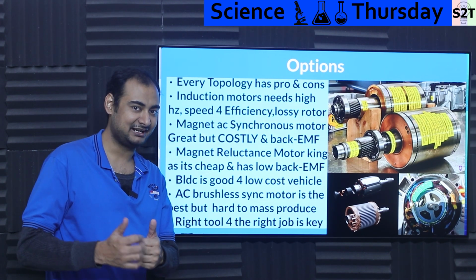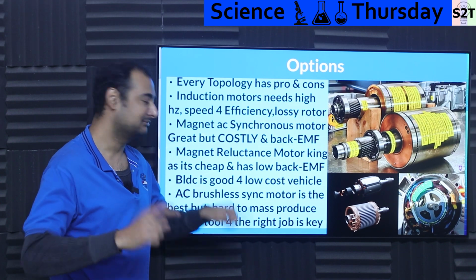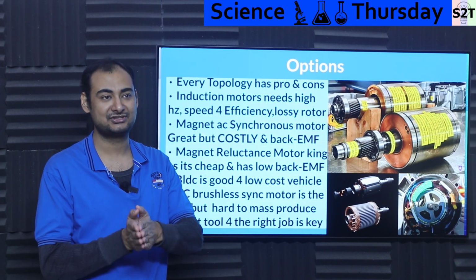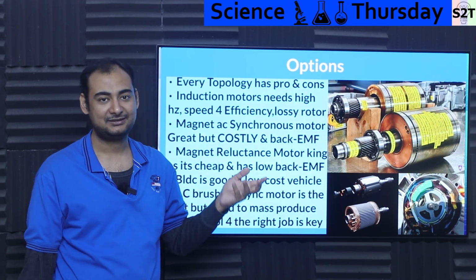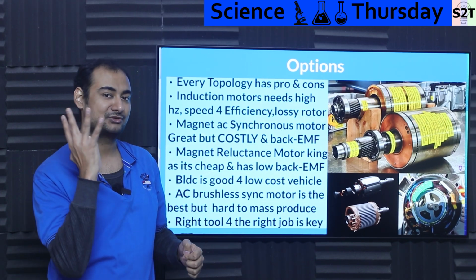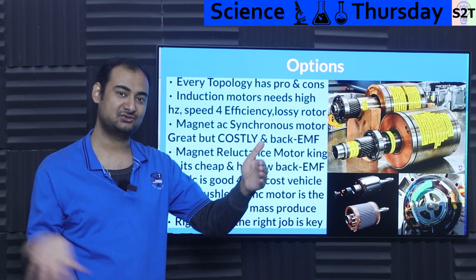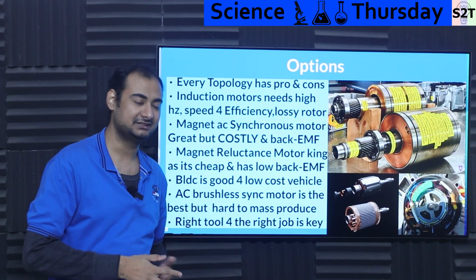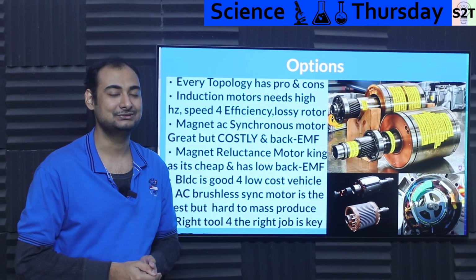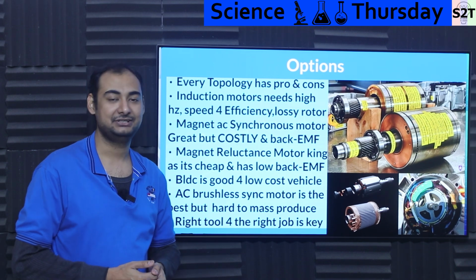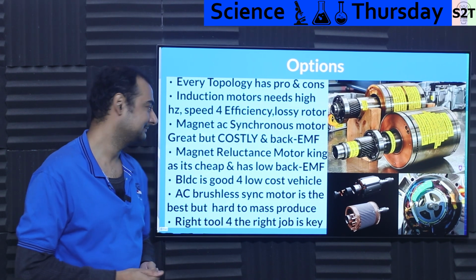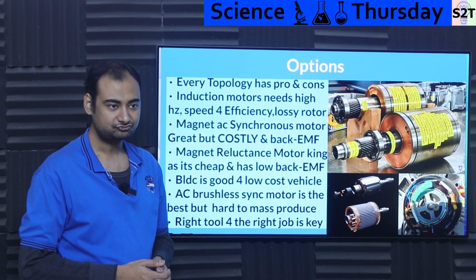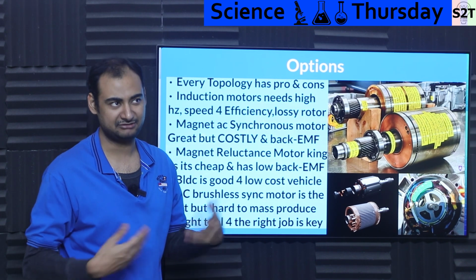Low RPM torque, everybody likes it. Low RPM efficiency, everybody loves it. The moment you're like, what if I want my car to go from very low speed to very high speed without a gearbox? You want your RPM to go from 0 to, let's say, 5,000 or 7,000. At higher RPM, it has a back EMF issue, because the rotor has so much magnet, it's going through, it's doing a magnetic sweep to your stator. The stator starts to induce what we call back EMF. It has to deal with that. You cannot turn off the magnet at high speed, so you're stuck. Fundamentally, that created an issue where back EMF became a hassle to deal with. So there are some penalties. Back EMF was a significant penalty, and cost made sure that nobody actually did more research on it.